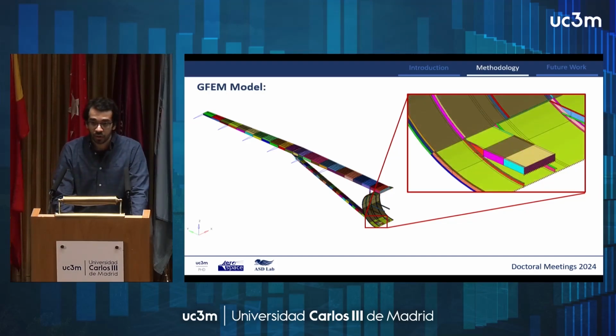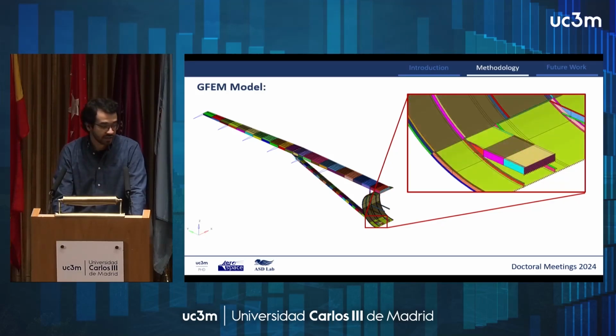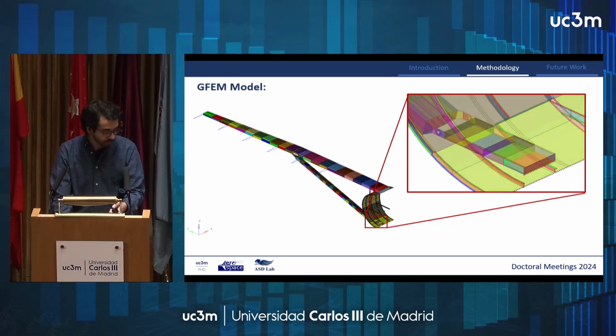Regarding the connection between the wing and the fuselage, we used the ATR-42 as an inspiration, so it is a high wing, and the connection is inspired by that aircraft. And then regarding the connection between the strut and the fuselage, we did a couple of experiments, and then we ended up with this solution, where we are taking advantage of the space below the cargo floor to maintain the airplane capacity, while having a wing box to minimize the mass and to distribute the loads to the frames of the aircraft.